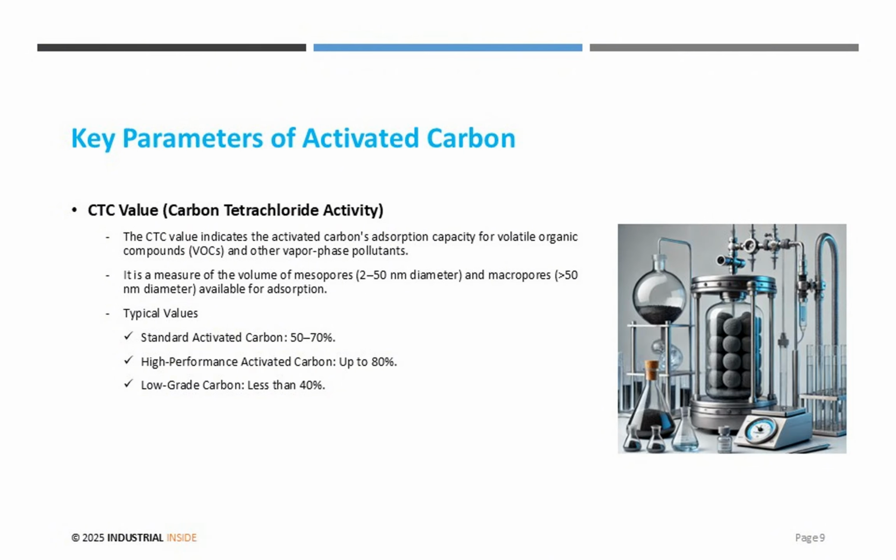The CTC value shows how well activated carbon adsorbs VOCs and other gases. It mainly reflects the volume of mesopores and macropores. Standard carbons range from 50 to 70%, while high-performance grades can reach 80%.